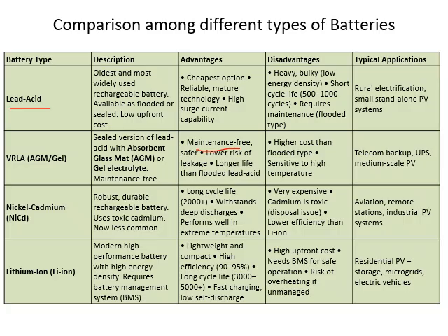Then for aviation, okay, remote stations, really remote stations, industrial photovoltaic system, or I'm not sure whether it can be used in the satellite also. So you should be using the nickel cadmium batteries, because first of all it's using toxic cadmium, so we don't want to use it in a densely populated area. But it has a long life cycle, right?